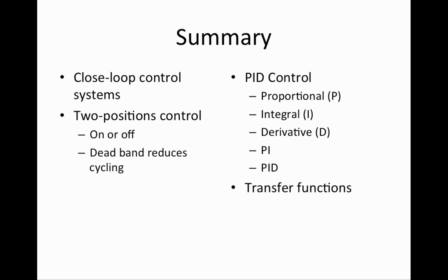So to summarize today's lecture, we learned closed-loop control systems, including 2-position control and PID control transfer functions and time domain control functions.